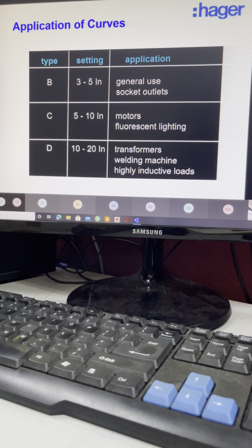Not just blowing the fuse at the plug top, it also trips the outgoing breaker and even the main incoming breaker. So it shows that there is no discrimination between the 13A fuse, the 15 or 20 amp outgoing breaker, and even the 63 or 40 amp incoming breaker.